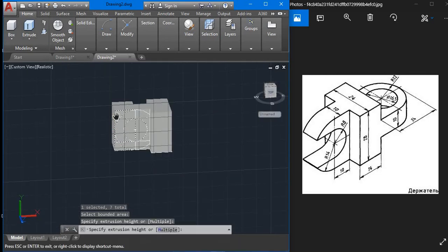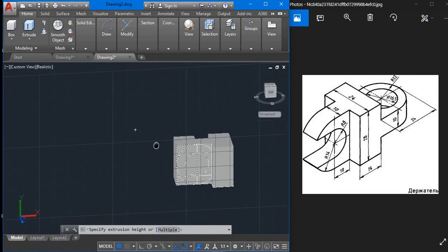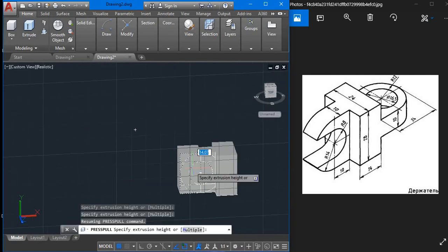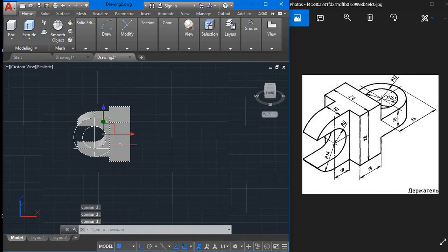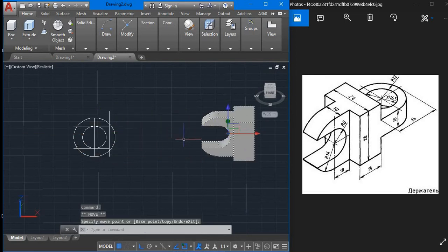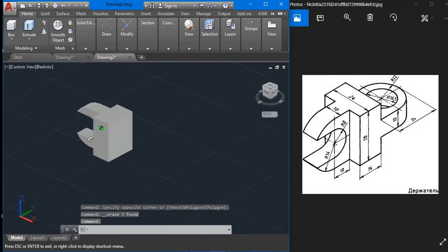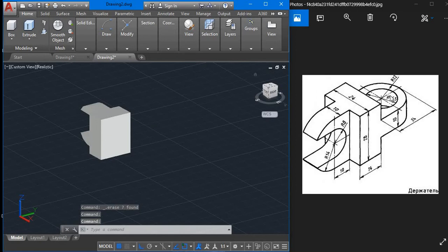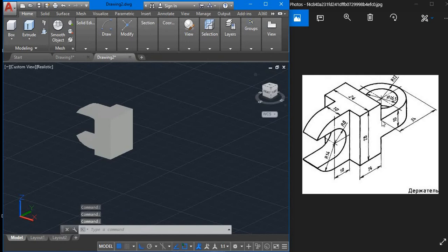Now when you press enter, you take your mouse away from it. Let's click just outside the drawing, and you have this. So the next thing I'm going to do is, let me shift this so the construction lines will disappear, so I know what I'm really having. So the next thing we will do is to get this back shape, with an extrusion. So we know that the thickness of that shape, and the total height is 28.